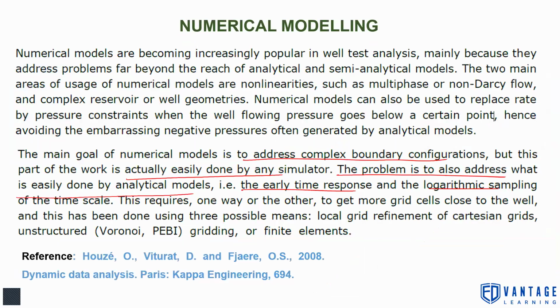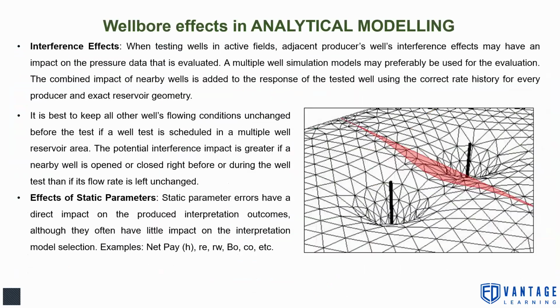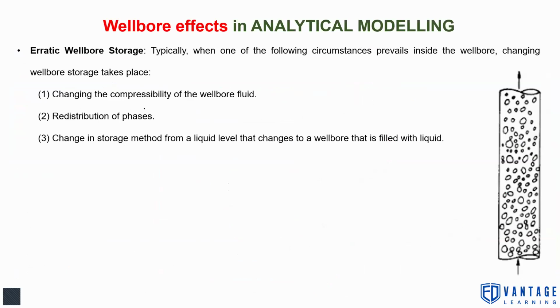So there are some well-bore effects in analytical modeling. That is what I wanted to focus on now. Well-bore effects in analytical modeling can be due to changing compressibility of the well-bore fluid. So as you're all aware, whenever we produce fluids, generally gas separation happens at near-surface depths, because pressure goes below bubble point pressure.